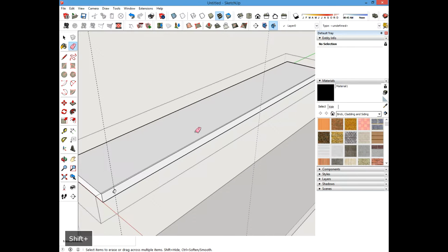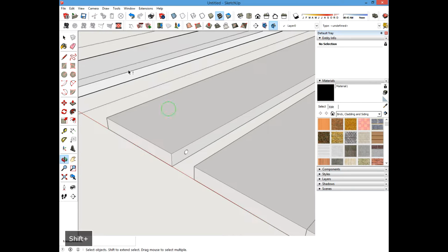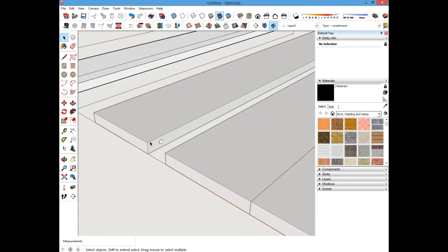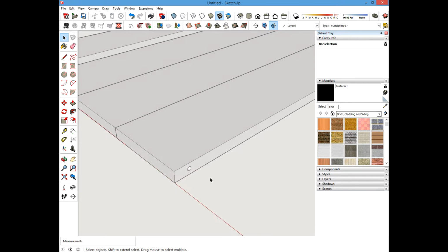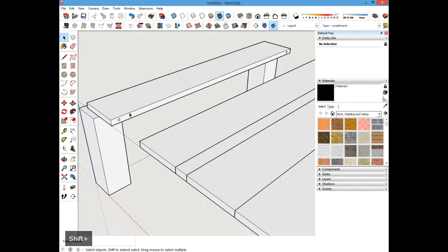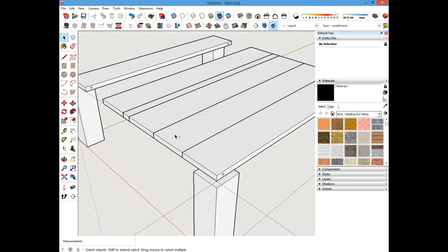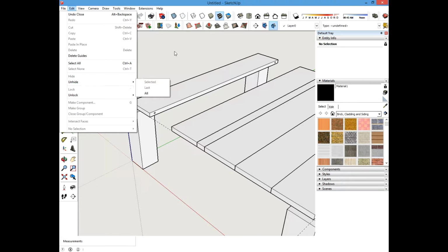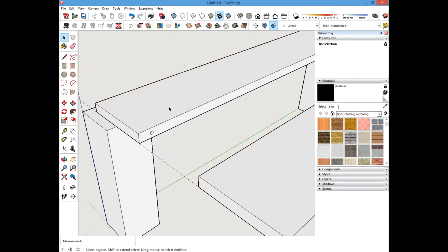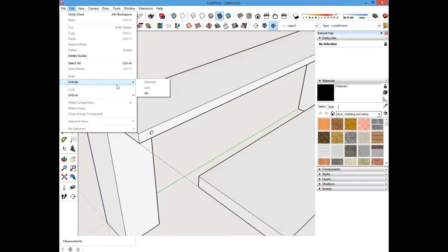So another thing to note, which is handy about this, is it's putting these holes in each component. So you don't have to do this for every one. You can just edit one of the components and it updates every single one of them, which is pretty convenient. So that would be an example of including a hole that we could put pegs in. And the thought process is you do it on the other board as well on the matching side, so that way you can insert pegs to align the boards. It's a pretty common practice in woodworking. It just helps them stay together better.